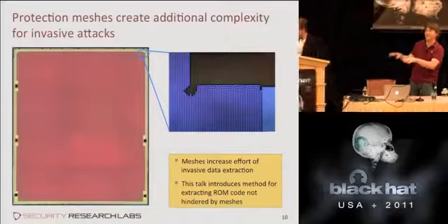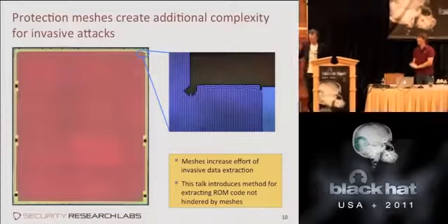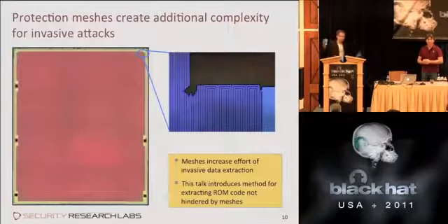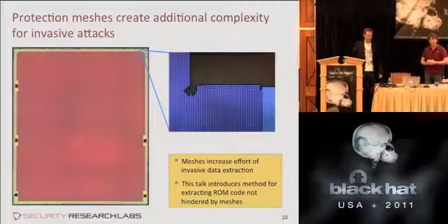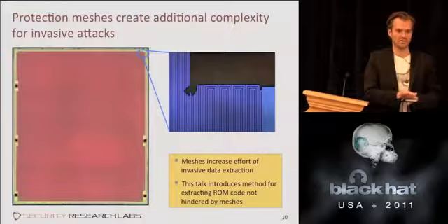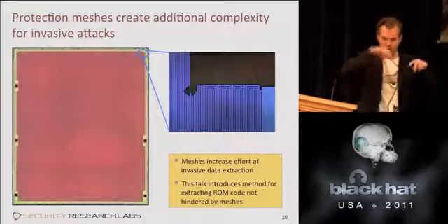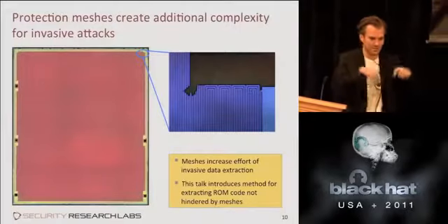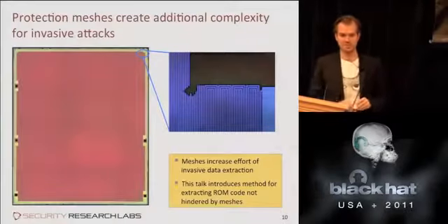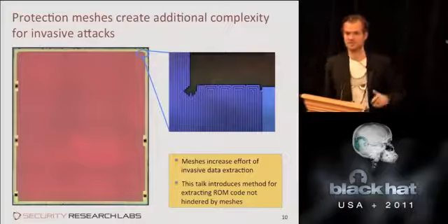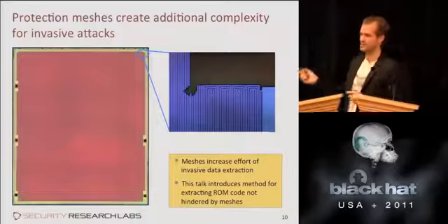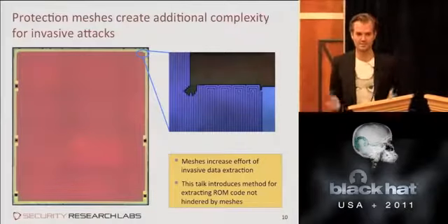One last example of how the smart card industry is fighting the one threat but not the other. The number one security feature on all the chips over the last 10 years was a mesh, a little snake of metal put on top of the entire chip. So no matter how tiny your needle is, there's no way of getting to the relevant points in the CPU core without breaking this mesh. And the chip notices, because this is a long snake, so it can test whether it's still connected. So breaking and making better and breaking these meshes has been part of the arms race.